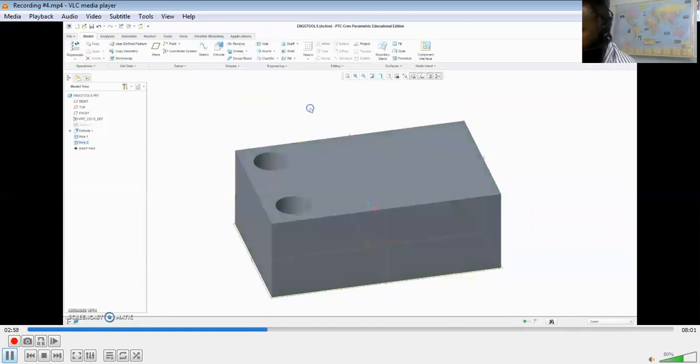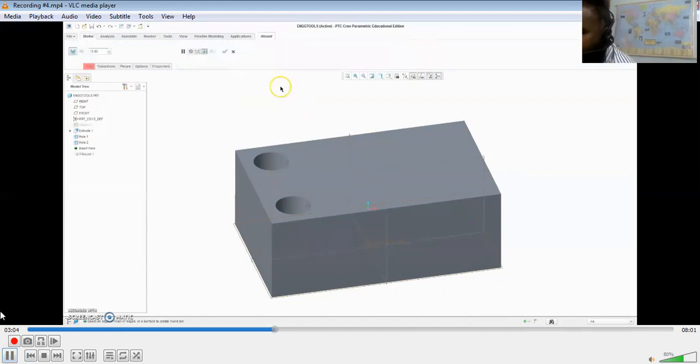What I'm going to do next is the pattern. Round feature. Round is like, the edges can be made smooth. Any given edge can be made smooth. So I just choose the round option and come and choose the edge.